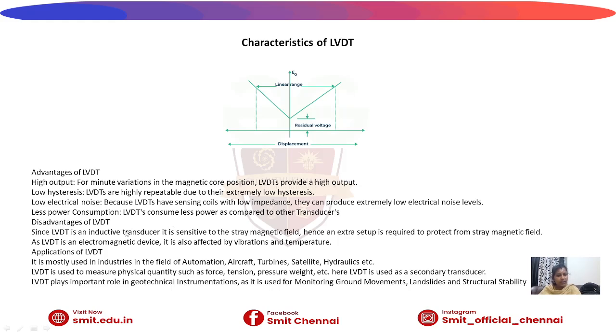The disadvantage of the LVDT is that it is an inductive type of transducer, so it is sensitive to stray magnetic fields. Hence an extra setup is required to protect against stray magnetic fields, right? Another one is that it is also affected by vibration and temperature because it is an electromagnetic device.